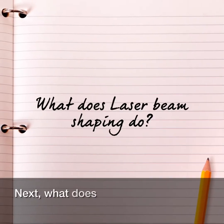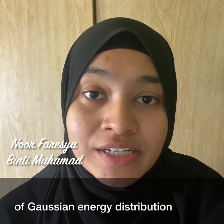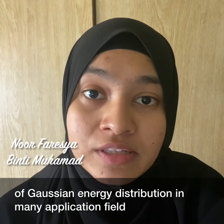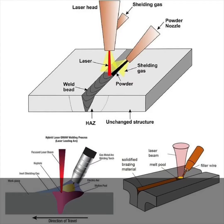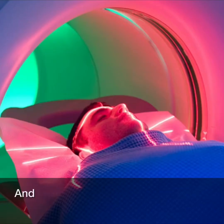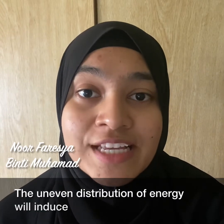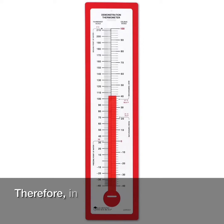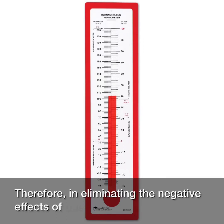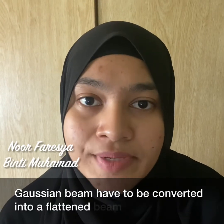Next, what does laser beam shaping do? The laser beam possesses the characteristic of Gaussian energy distribution in many application fields, such as in laser processing, laser welding, and laser medicine. The uneven distribution of energy will induce high local temperature. Therefore, in eliminating the negative effect of uneven temperature, the Gaussian beam has to be converted into a flat-top beam with evenly distributed energy.